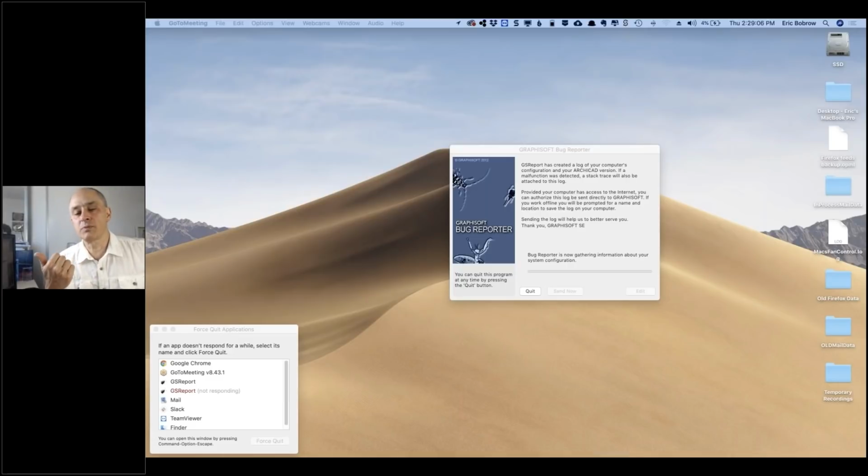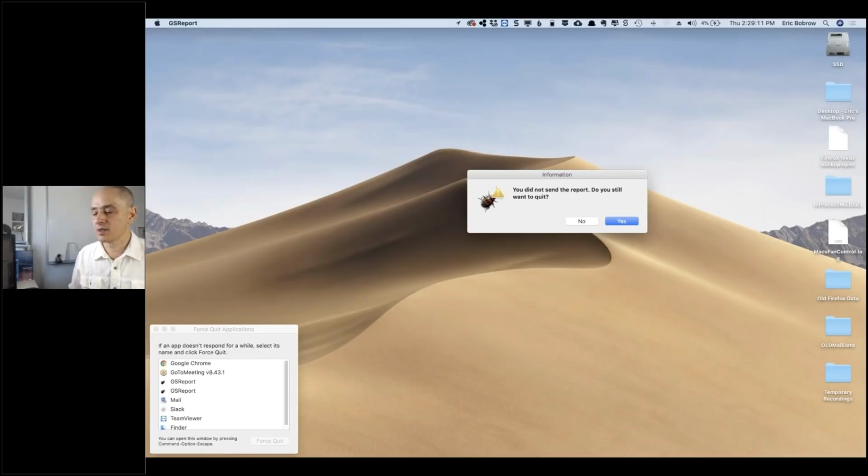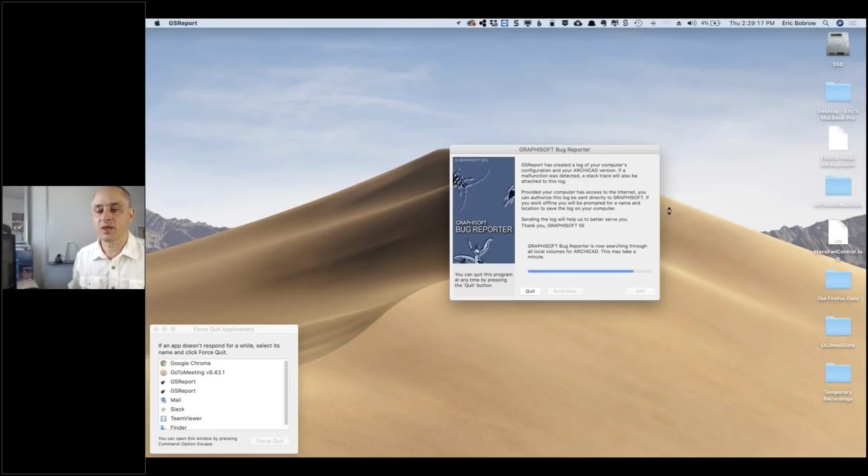So a couple of tips. One is that you can maintain the modules within the same file instead of in a separate file. You can have it on a remote story. This is what Tracy Stone's office has done. By doing that, or having multiple stories down below, you don't have to have multiple files open, and it becomes easier to update things. So you can review the approach that they used in that session that we went over.